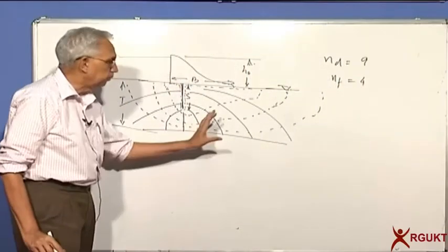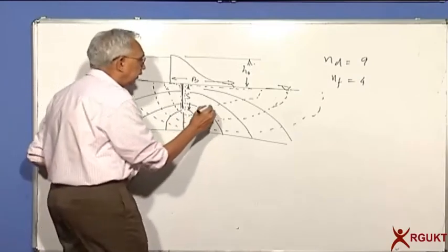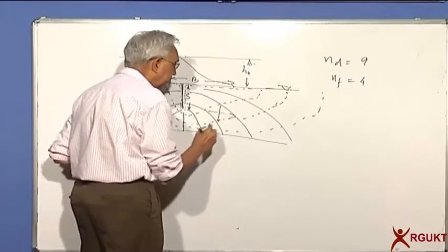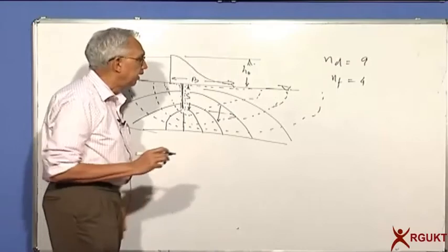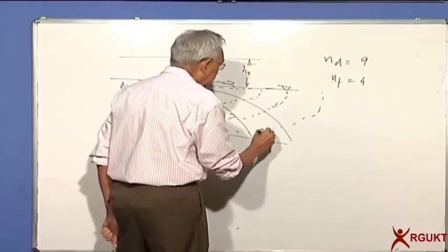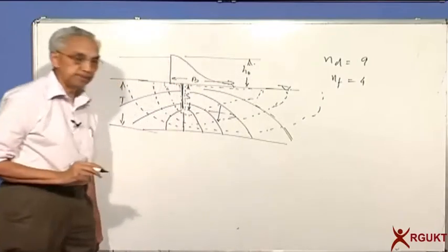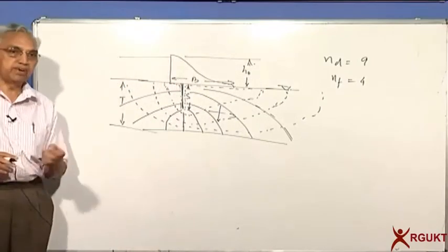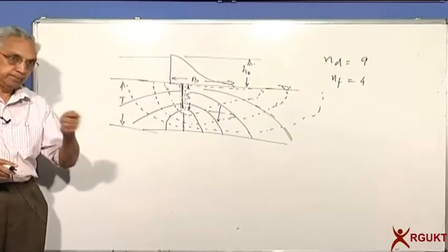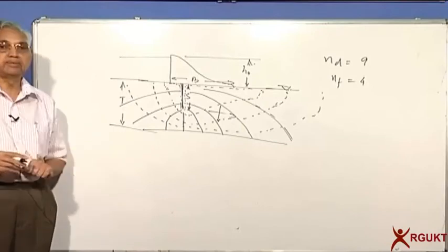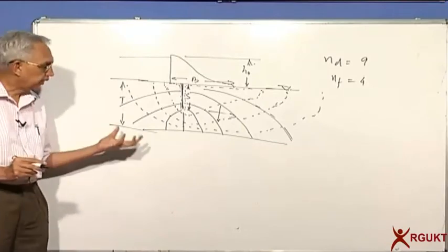As long as you are able to maintain a rough square shape, this is a very good one. Maybe I should have changed it slightly here. In the presentation, I'll show you more accurate ones. We cannot draw it within 5 minutes. A good one, you have to keep practicing any number of times to get this flow net correctly.